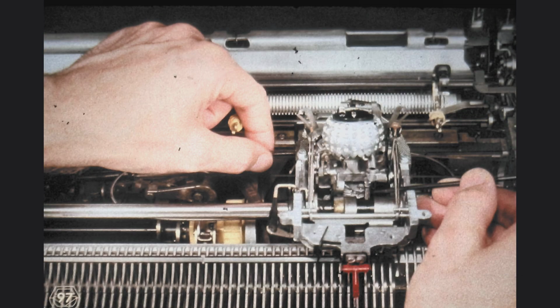We use the left hand to push a little bit of rotate tape into the carrier cavity. The extra slack allows us to apply a spring hook behind or under the rotate tape at the point where it is connected to the rotate pulley, between the rotate tape and the carrier.